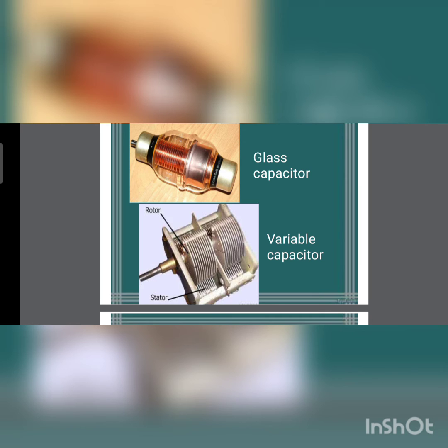Then another type of capacitor is variable capacitor. The capacitors with varying amount of capacitance are known as variable capacitor. Certain ranges of values are provided in variable capacitor, and based on the required values, these capacitors are chosen. This type of capacitor consists of plates made up of metals. Among these plates, one will be fixed, the other will be movable. The range of the capacitance provided by this capacitor is from 10 picofarad to 500 picofarad. The most popularly used variable capacitors are tuning capacitor and trimmer capacitor. The trimmer capacitor can be easily used on the printed circuit board, and second, these are used in receivers of the radio.